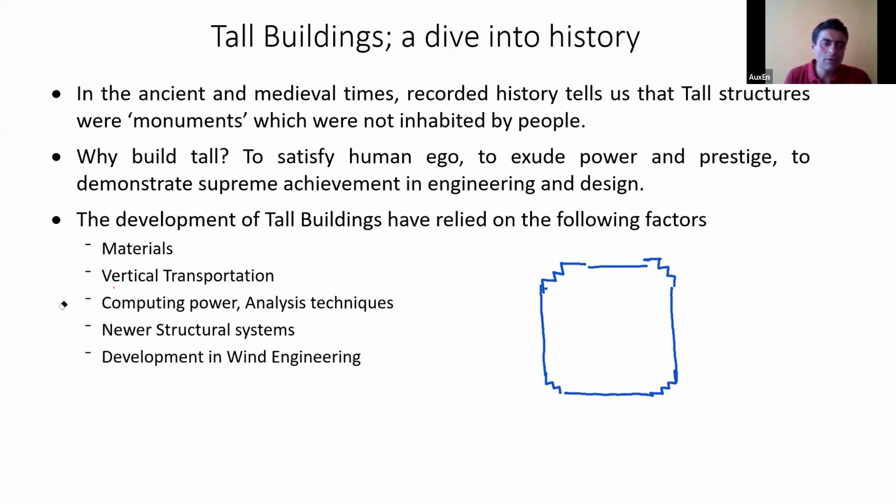So a good wind engineer will always suggest the way in which the wind loads can be mitigated, and good plan shapes, good plan sizes, good geometries that you would like to provide in order to minimize the effects of wind. So developments in wind engineering over the past 50-60 years have also enabled us to construct tall and taller.